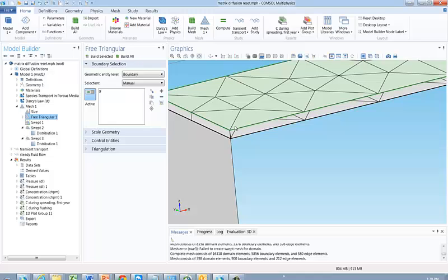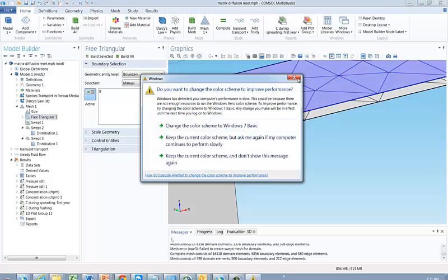In this case, we only swept one element, but we got this broad, thin element. If we didn't do that, if we just meshed this volume with a tetrahedral mesh, I would have got many small tetrahedrons in here. So there would be many more elements in this thin layer, and it would make the problem very cumbersome to solve. So this is a much better geometry for that kind of a long, broad, thin layer. Okay, so we need to continue on with this process.